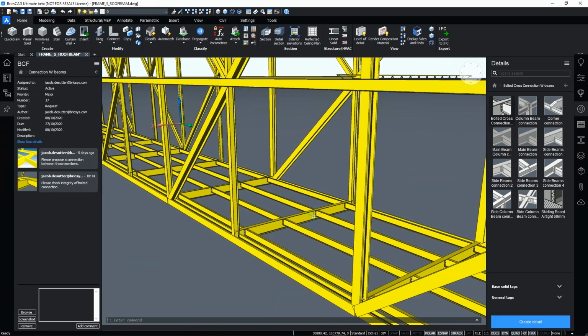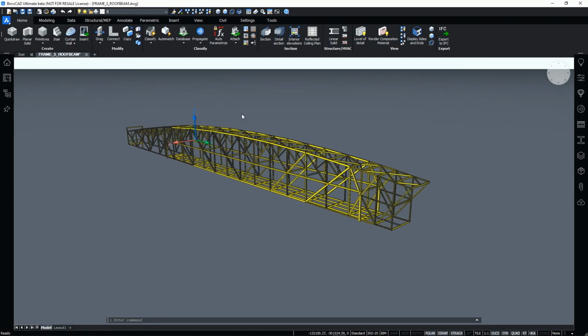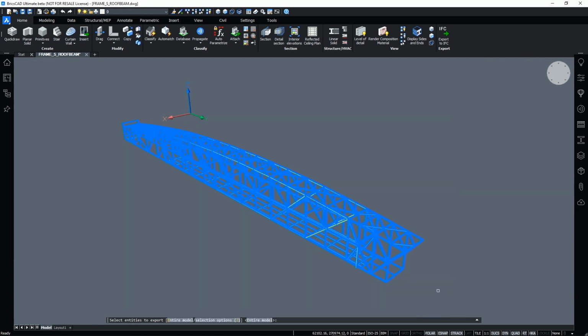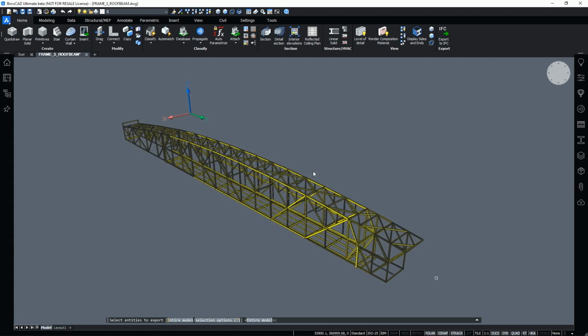A second part of the open BIM workflow is working with IFC. In V21, we have worked significantly on performance and stability of IFC import and export, but we also added several new improvements, like import and export mapping. This allows users to map internal BIM types to IFC types, which gives them a lot more control over how entities are exported and imported to IFC.